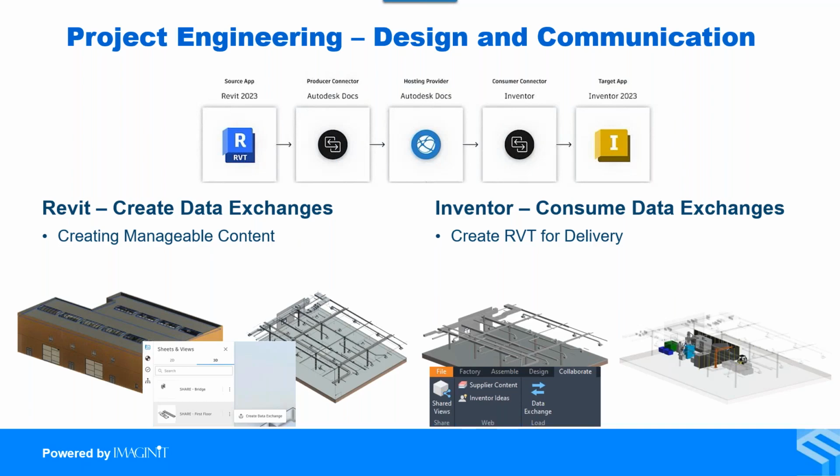Now, in Inventor, I actually have the ability to go into the construction cloud, into Docs, and say, I want that data exchange to come into Inventor. Data exchanges, even though it sounds like a handshake back and forth, is one directional. You go from Revit with your intent of going to Inventor. And these data exchanges are getting enhanced. There's also data exchanges coming for Power Automate, things like SharePoint, things like that. But we're focusing here on the modeling data, of course.